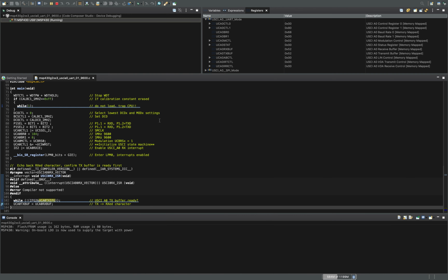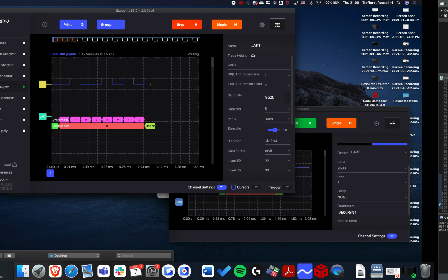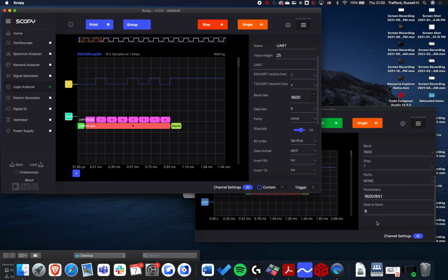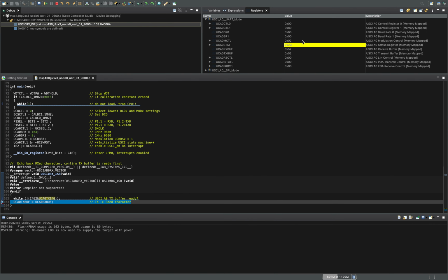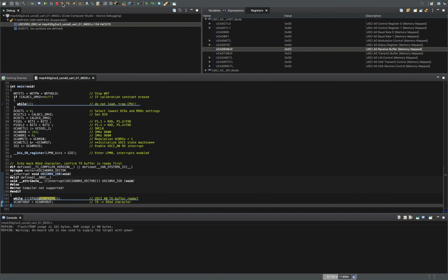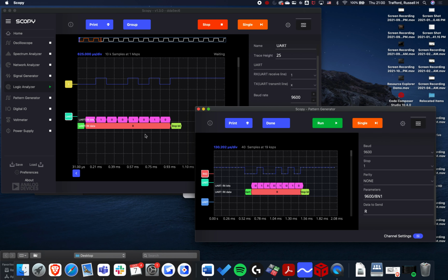So what the debugger is letting you do is put in these debug points or breakpoints to let you see what's happening. So just to show you I'm not creating something out of thin air, let me send another R packet, pause the debugger, and let me show you that you're sending what's in the receive buffer. I'm going to change this. What if I wanted the letter S? Let me make it 53, so I hit enter. Now when I go to the next step, let's see if it actually listened. It didn't. Great. Sometimes it does change, sometimes it doesn't. But I still get R.